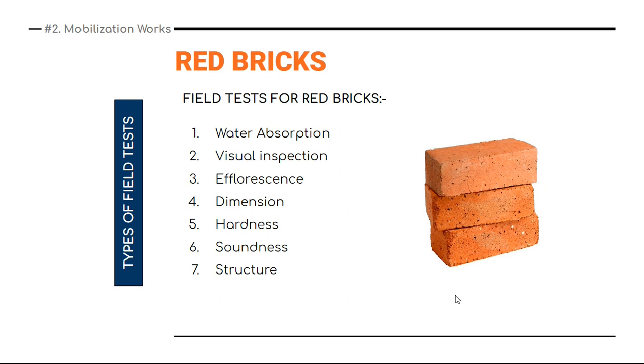After arranging 20 bricks accordingly, the practical size and theoretical size should match. If there is a lot of difference, then reject those bricks immediately, and they should be of proper size and shape as discussed.